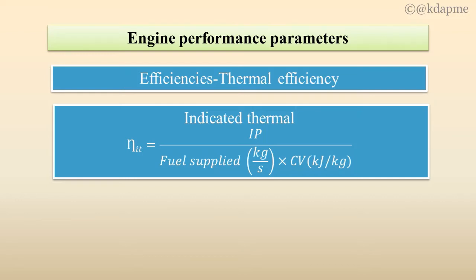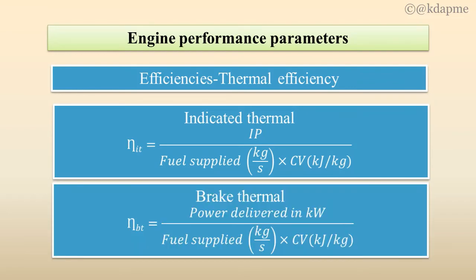This equation is used to determine indicated thermal efficiency. Similarly, brake thermal efficiency, eta BT, is the power delivered in kilowatts divided by fuel supplied into its calorific value.